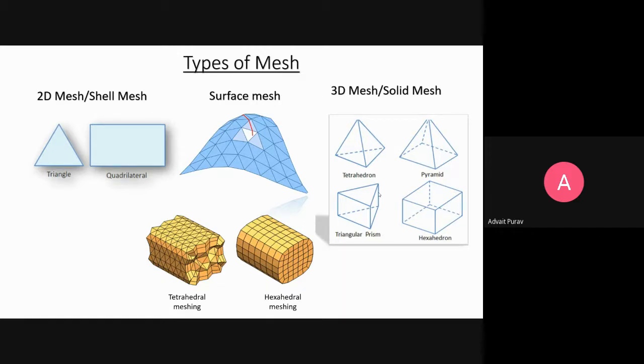But the software has features to solve those issues. They have fill holes or fill cavities options, or you can reduce the tolerance of your mesh, or there is a mesh control option in simulation software where you do this. So your question is absolutely valid: shapes change and problems come up in meshing, but you have to resolve them with experience. Do we have to resolve it manually, or does it happen automatically? Manually.